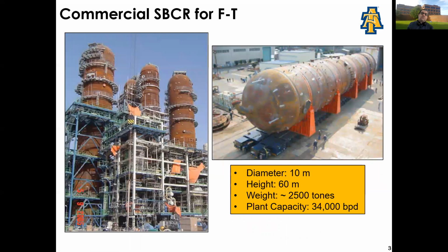The most popular one, or the most famous one in these types of presentations for Fischer-Tropsch, is this reactor by Sasol in Qatar. And as you can see, the reactor is 10 meters in diameter, 60 meters high. It's a huge type of reactor.